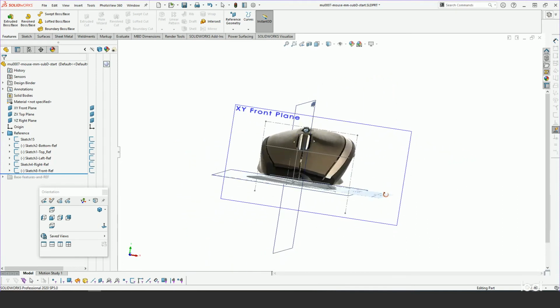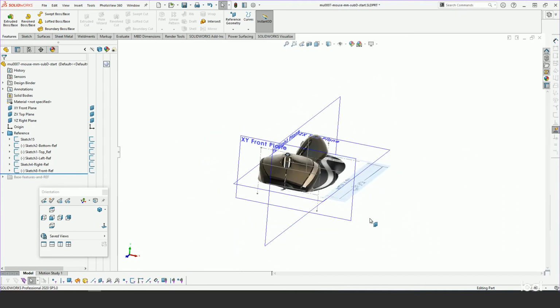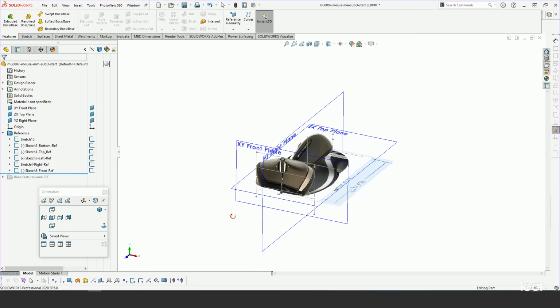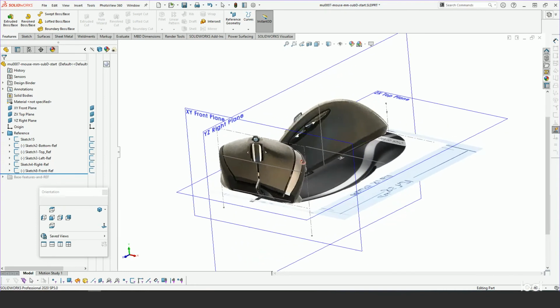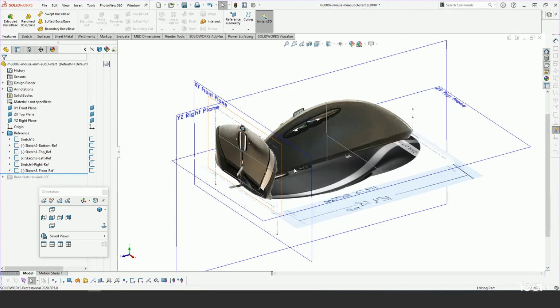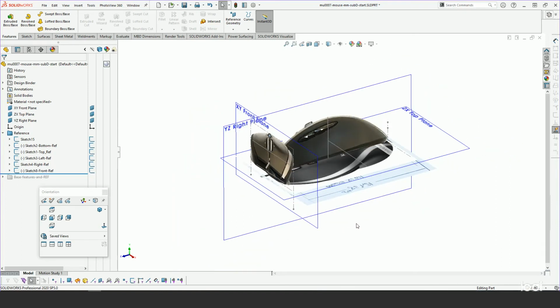Now, with the perspective of photographs, especially ones you get on the web, they are somewhat distorted. So you have to keep that in mind, that between photographs you're going to see discrepancies when you're using this method for reverse engineering. So just be mindful of that. If you take photos yourself of products, just make sure that you're at least like 10, 12 feet away, and then using telephoto with your phone or SLR camera would be the best method.